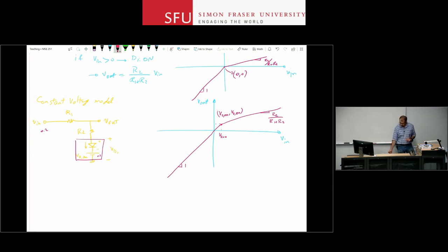There's an example on the next slide where you have 3 diodes in series and you're asked to solve the problem using a PN junction diode model, where the exponential relationship between ID and VD makes the equations a little bit harder to solve. You need to solve it with iterations, versus the constant voltage drop model, with the assumption that VD on is only 0.7 volts.